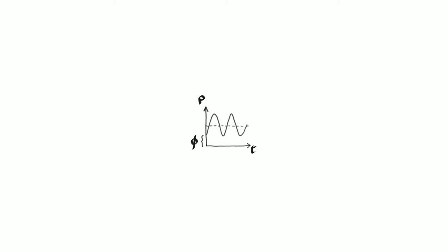If the recorded sounds are of opposite polarity, some of their frequencies could cancel each other out, making the sound thinner. This can be very difficult to pull off, especially with multiple sound sources. The best result is achieved by listening to the different sources, switching polarity of each source in turn, and selecting the result with the best sound.